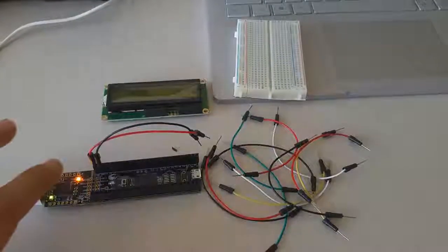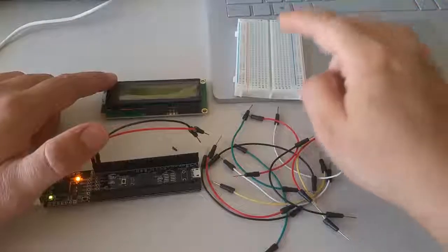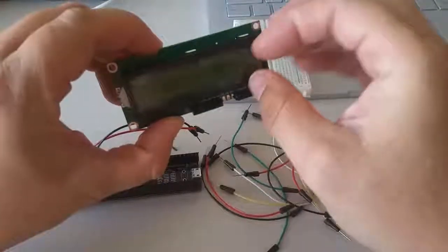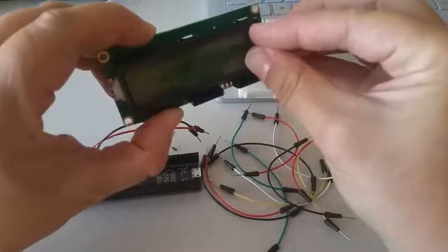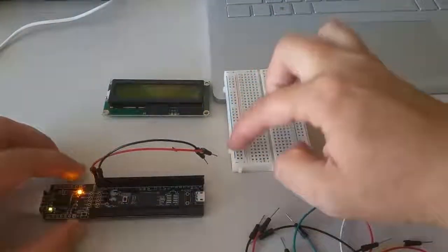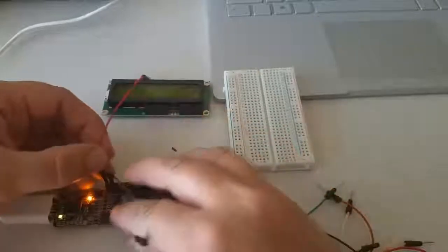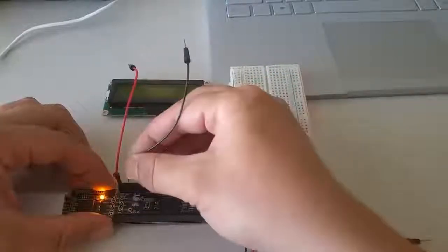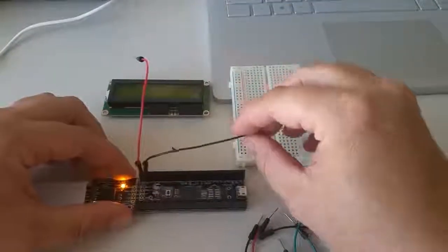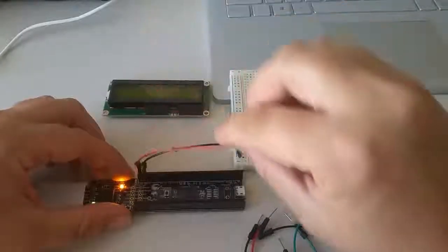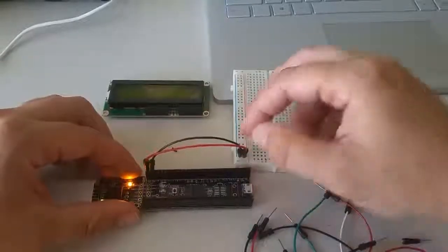Okay, gather together your PSoC, your LCD screen, your solderless breadboard, and a bunch of wires. If this protective covering on your LCD screen is still on here, you can go ahead and pull that off. Now, the first thing I'm going to do is set up my power and ground rails. So I'm going to take one wire and plug it into VDD, and another wire and plug it into GND. And then I'm going to plug the wire that's GND into one of the pins on this ground rail. And then the VDD wire I'm going to plug into the power rail.